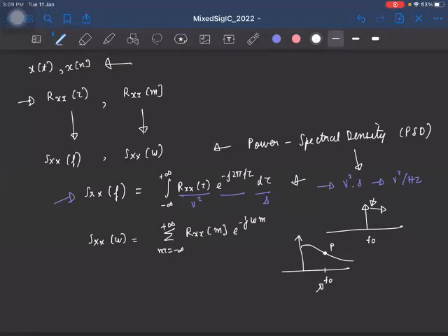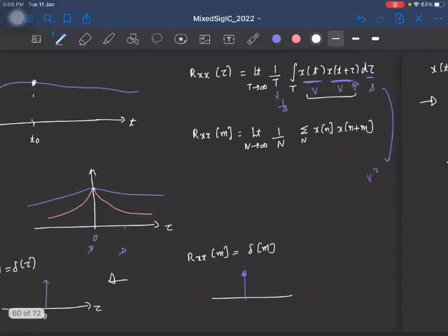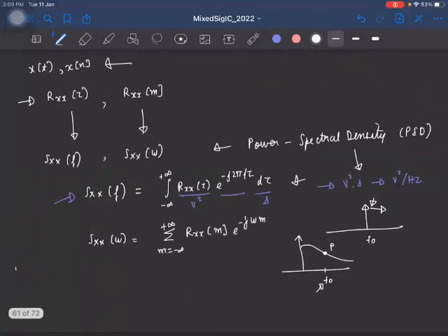Okay. Well, so if we take this case where the signal was completely independent of its own adjacent samples, so if we have an autocorrelation function of delta, what is the power spectral density? It is a Fourier transform, which is flat, which is constant, right? So it's going to be a constant like this.